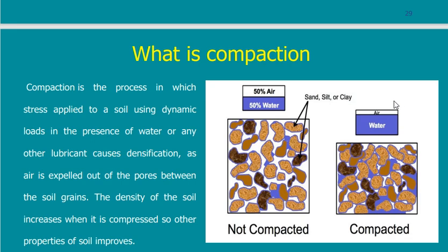So if I have clay, it means that I don't have very good permeability. So in this case, once I expel all of the air, the remaining settlement may take years to happen. That's why we said that there is something called immediate settlement. Immediate settlement is the part that we are dealing with here. Anything you put on top is still going down till you find that all the white spaces have changed to blue. In this case, we change to a consolidation case.